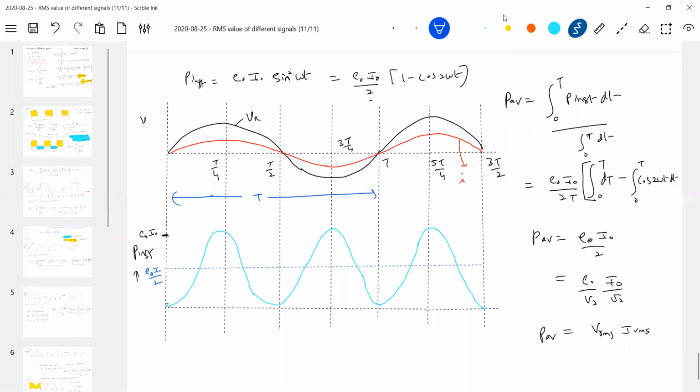Okay, look at the bulb now. This resistor R is nothing but a bulb. When you apply an AC signal, the power dissipation across the bulb will vary. It becomes maximum, again zero. But we never see this variation, and if the power dissipation varies, the brightness of the bulb should also vary. Do we see the variation of brightness like this? In one cycle, the brightness becomes maximum only twice. We never see this variation. What we see is almost constant brightness. We feel like that, but in fact the brightness is varying.